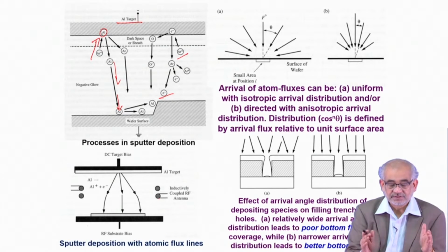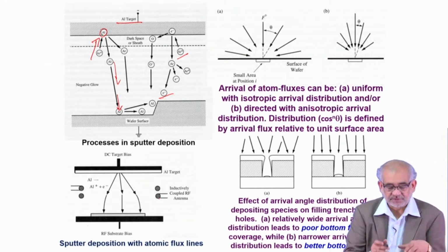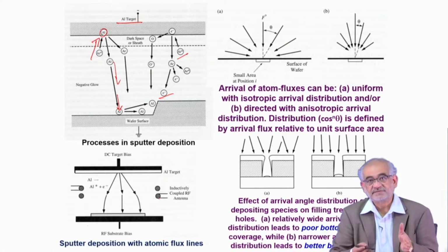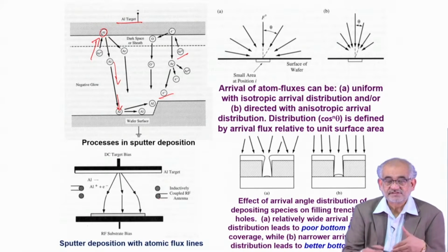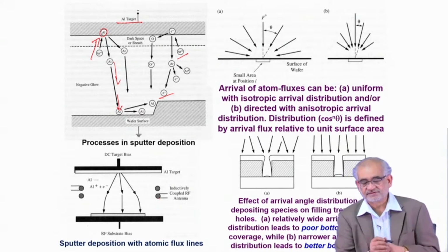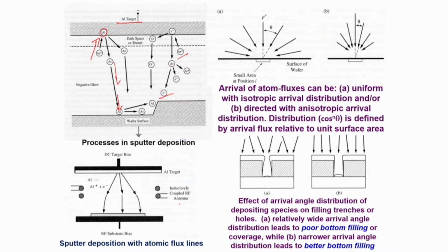One possibility is that you confine the plasma by applying a high flux, high power magnet, typically a magnetron, and then you call it magnetron sputtering. Similarly, the frequencies of the sputtering can be changed from a normal electrical power supply to an RF coupled power supply, and accordingly there could be certain differences. So this arrival will create the overall geometry, or overall thickness, and uniformity will govern that.